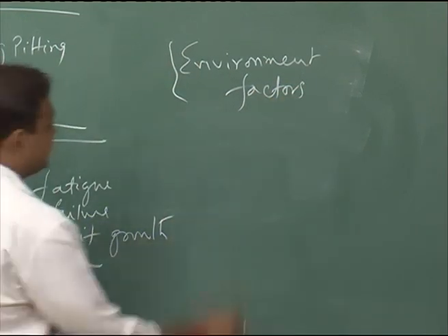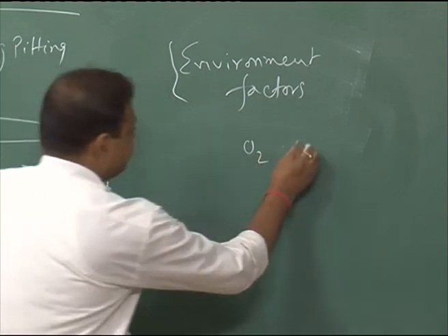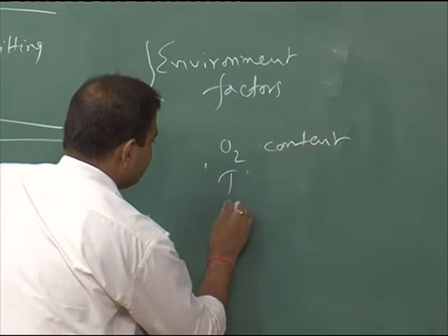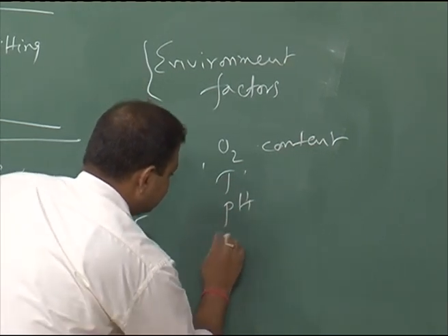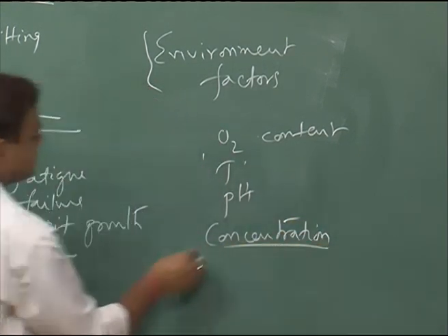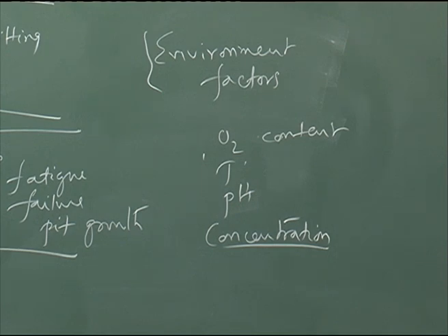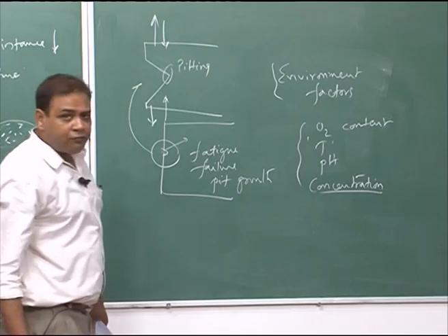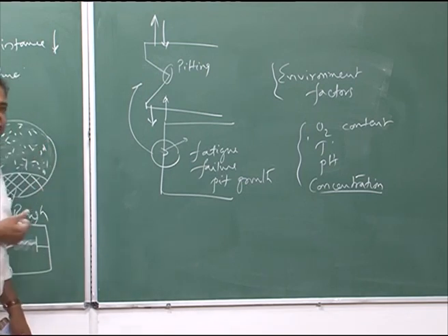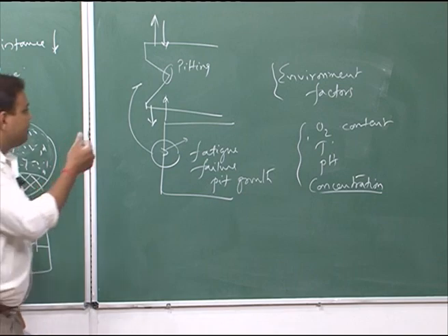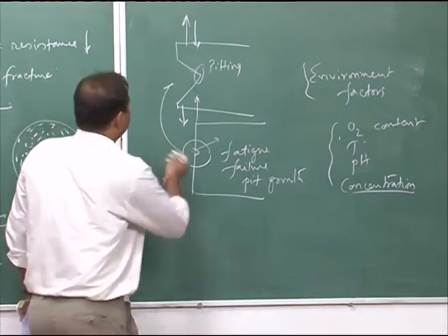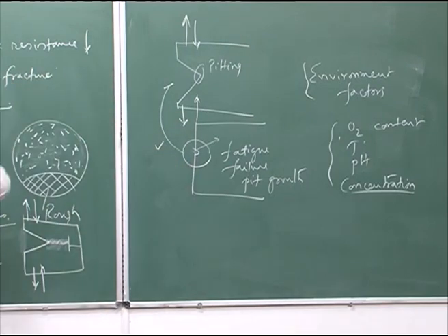When we come to environmental factors, definitely oxygen content, then temperature, pH, solution concentration, corrosive species concentration, all these things are to be taken care of. And also we have to see that there is no crevice formation, and the material should have inherent pitting resistance. Those can prevent corrosion fatigue.